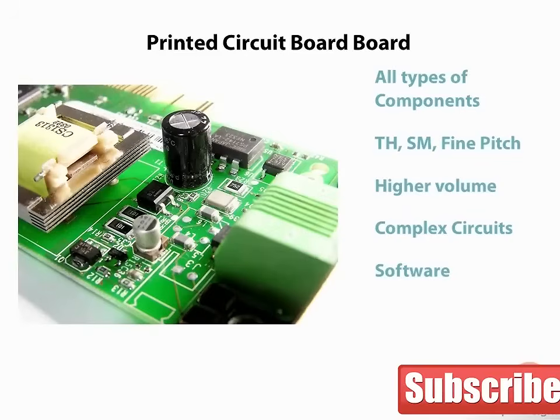While it is possible to make a simple PCB without software, not many people do this anymore with the advent of accessible PCB software. There was a time the only way to make a prototype PCB for the experimenter was to take a board with a full copper plane on it and apply resist to the circuit traces. The whole board was then dipped in a very strong chemical that would etch the remaining copper away, leaving the required traces. Holes then would be drilled, and then finally you had a crude board.